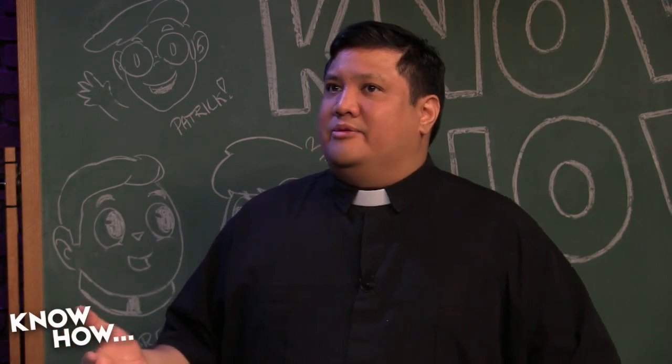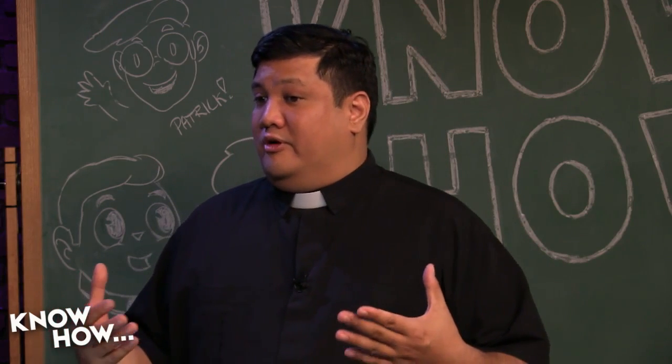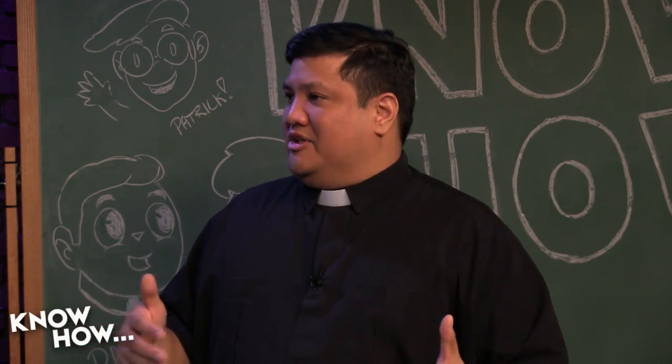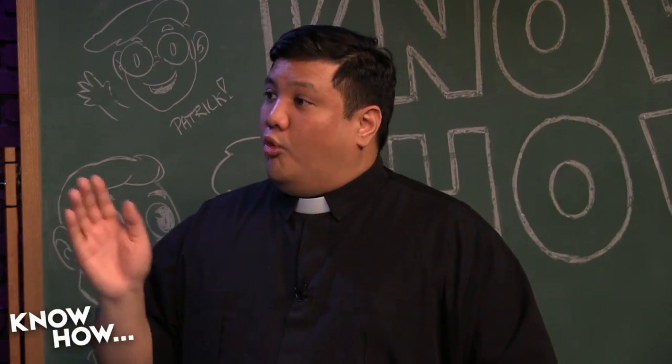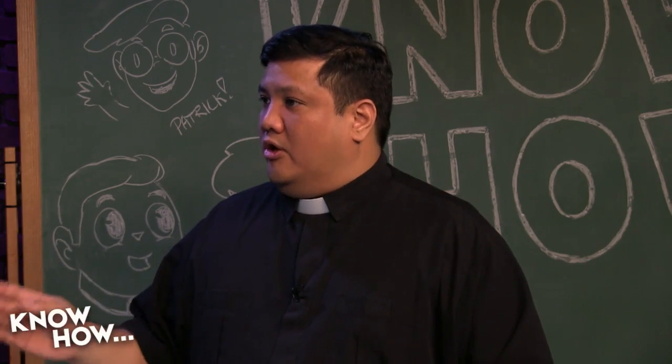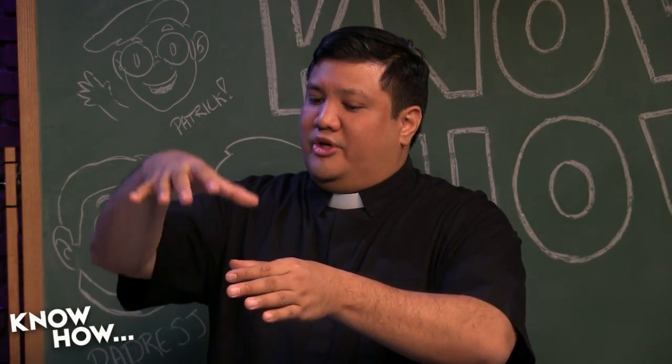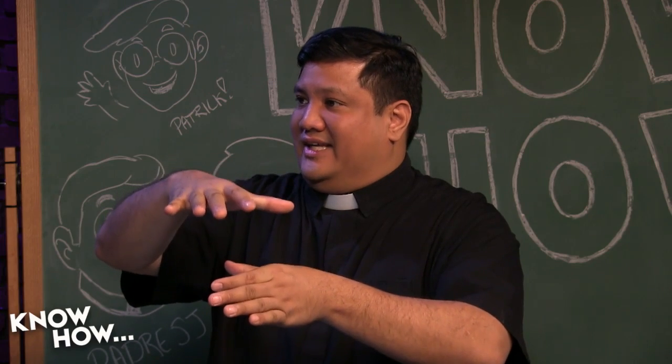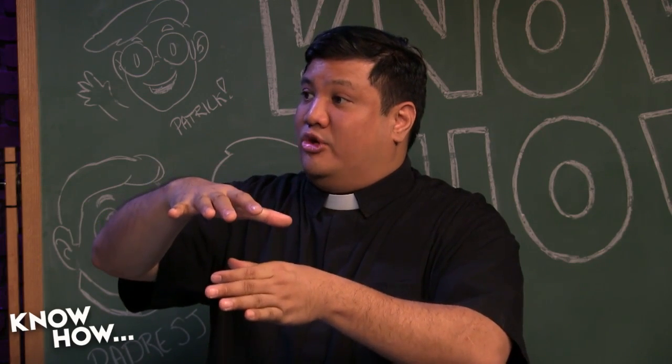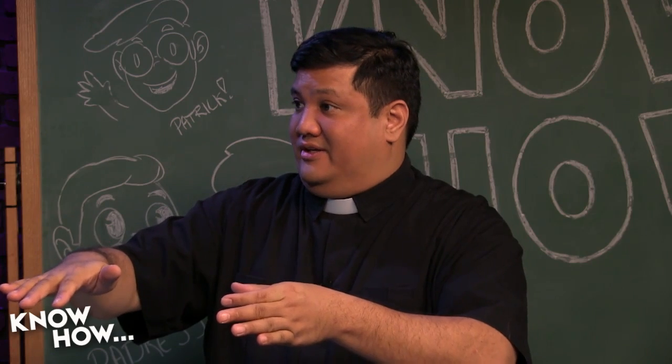Then, right about the time that I was in grade school, we started being able to afford, and by afford I mean I was able to dumpster dive for the equipment that let us use EPROMs, erasable programmable read-only memory. What you would do is expose it to intense ultraviolet light, and when it got hit by the light, it wiped the memory. There was actually a little window in the top of the chip. You've seen those. I think I've seen those, on game cartridges, like early Nintendo cartridges.